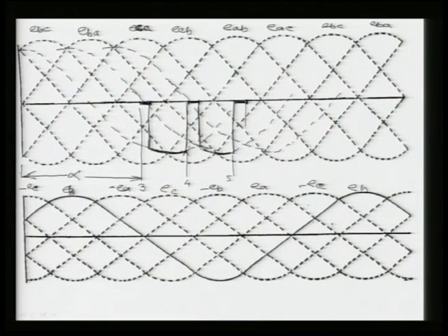So it will follow suddenly here, means this voltage is 1.5 EB, that is a plus. This voltage here is minus 1.5 EC, and this voltage is 1.5 EA, which is minus voltage here, and then we are giving the gate pulse at this point to your 6, and then this will be 0 here, and it will go for 15 degree again.